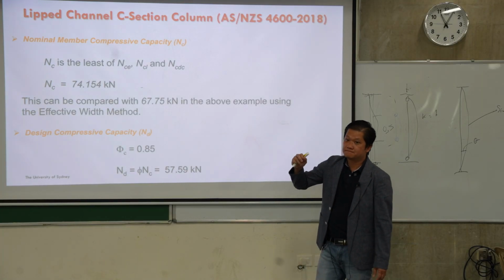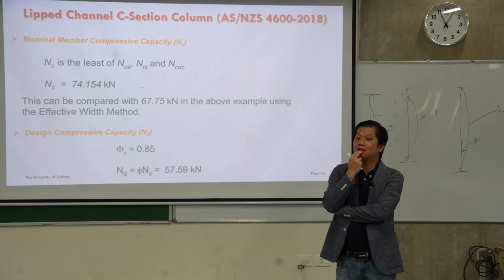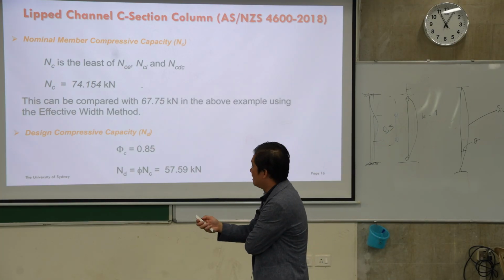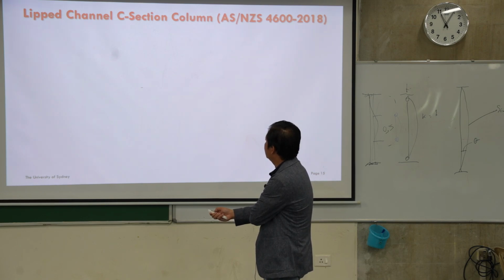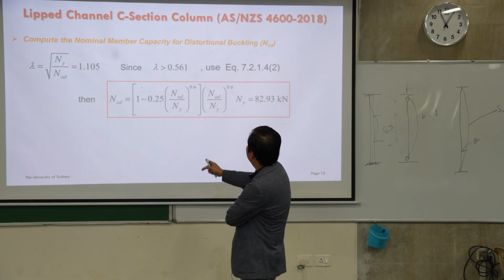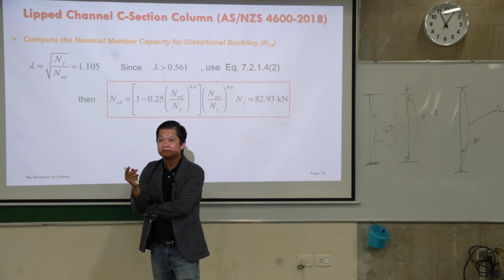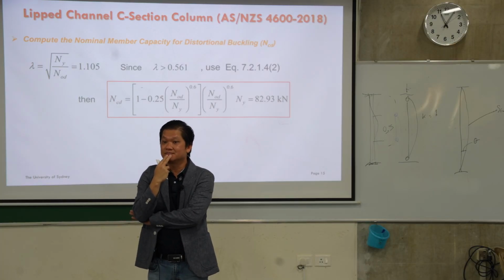Sir, in the previous distortional capacity, that is the inverse. Yeah, and what? So the gross area times yield stress. Which one? Ny, in distortional capacity. In distortional buckling, for lambda, yeah? Ny. Ny, yeah? That is A gross times Fy, the gross area times yield stress.